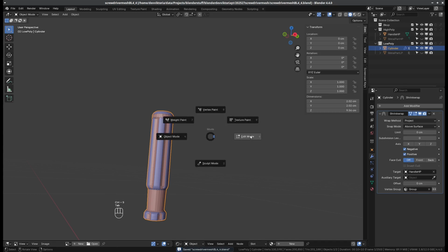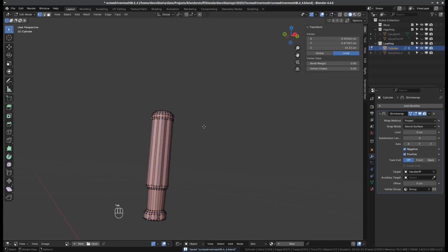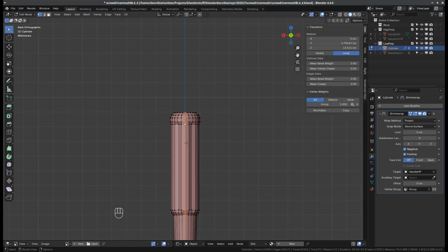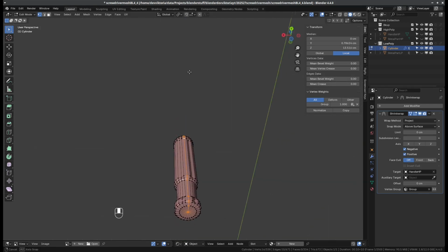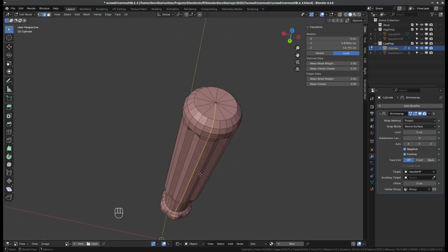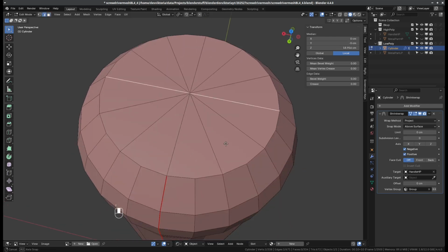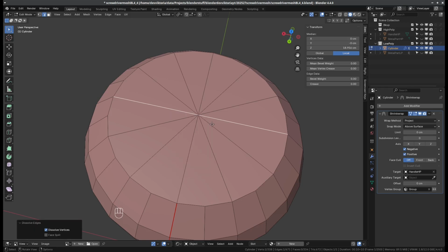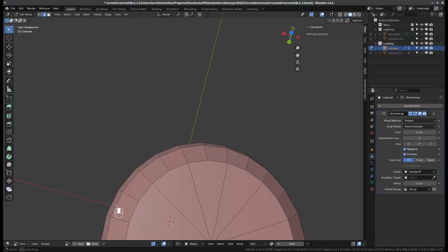And also what we have to do now is some UV editing. So let's grab this guy here. Shift click this one. And let's shift click this one and Q mark seam. What is this edge here? But I think I am going to select only edges and faces.